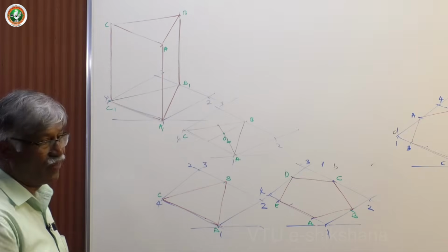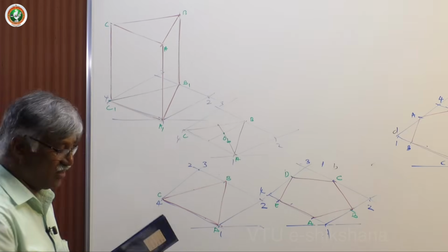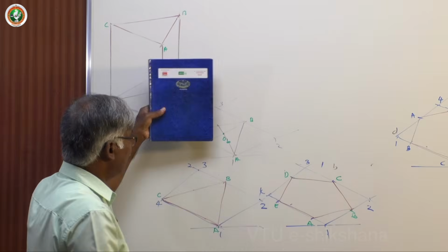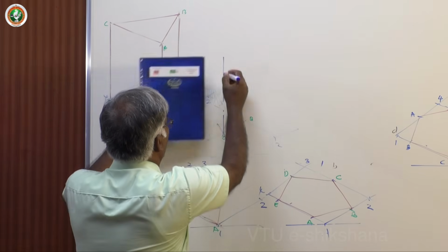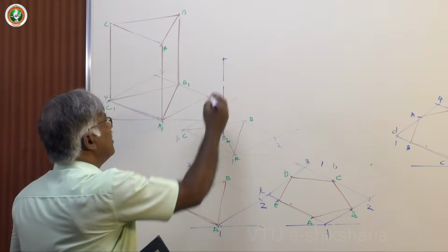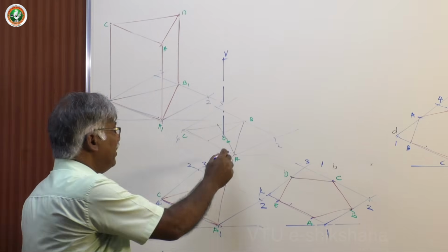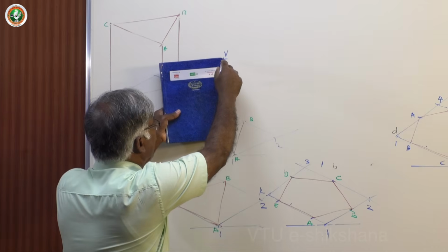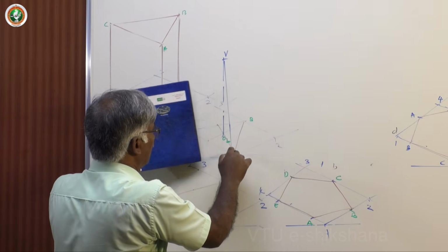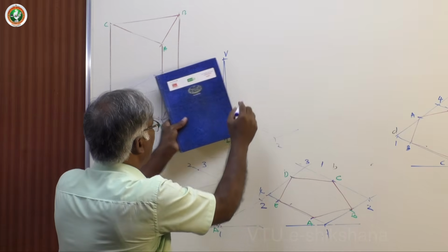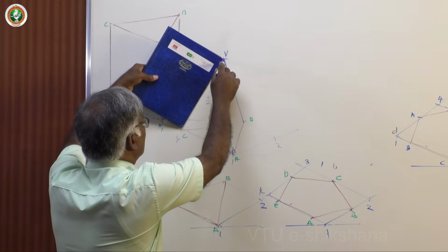Now project up, because the axis is always perpendicular to the base. Take this 60 with the convention available, 60. This is V, the apex. Join A with V, A with V, okay. Then B with V, the apex. Then C.